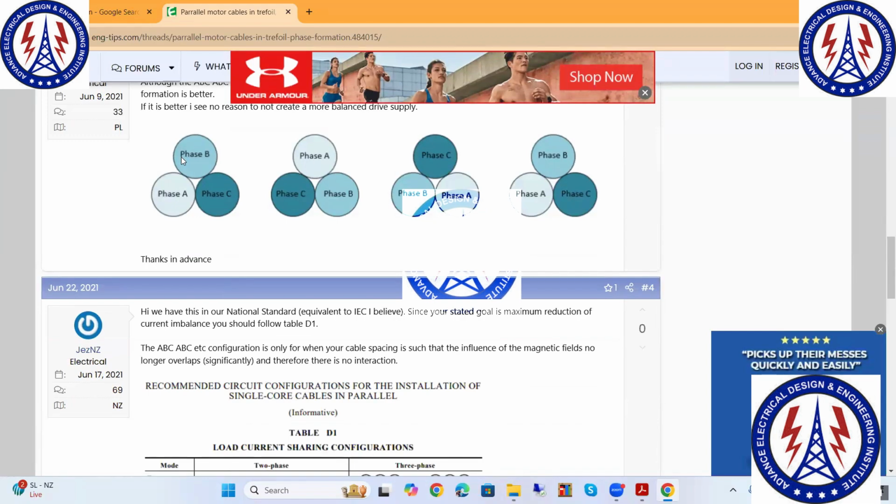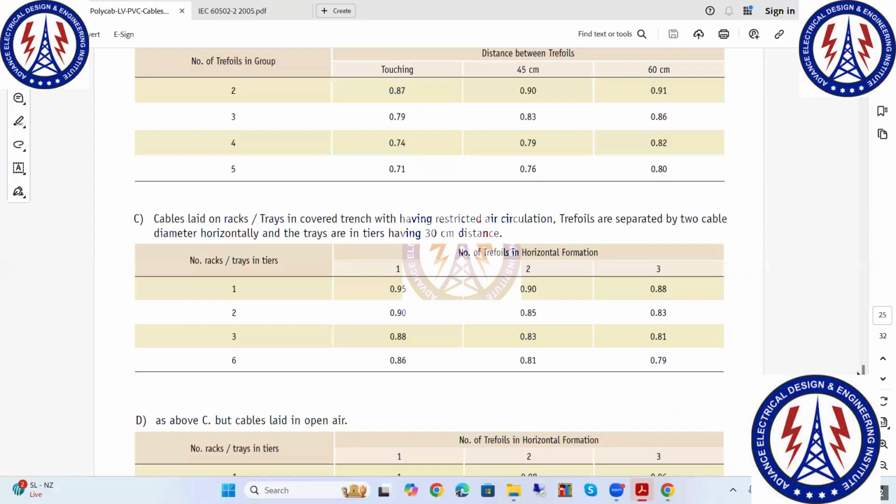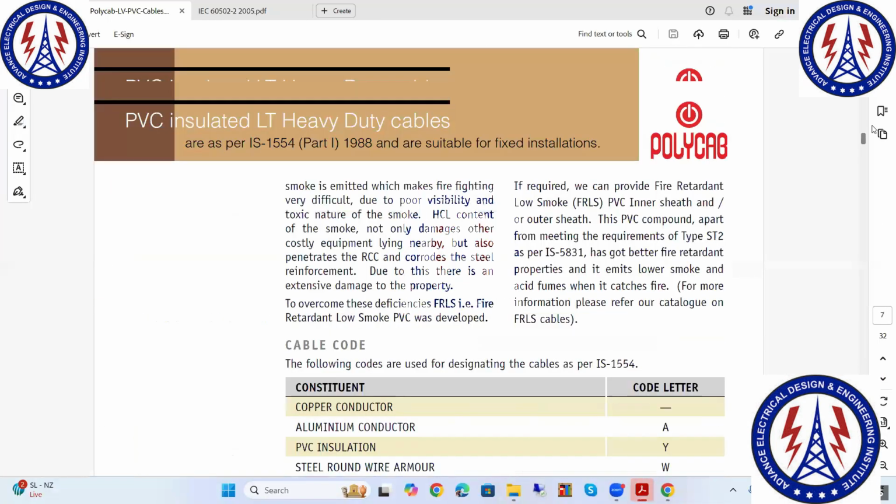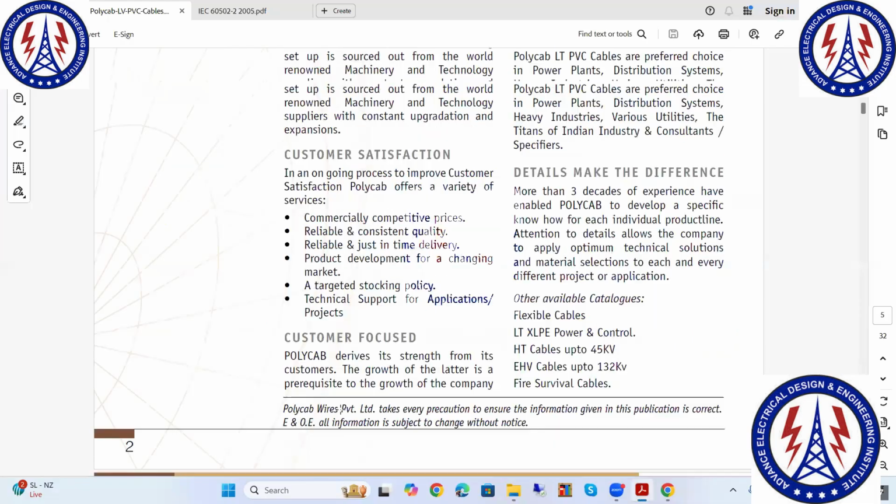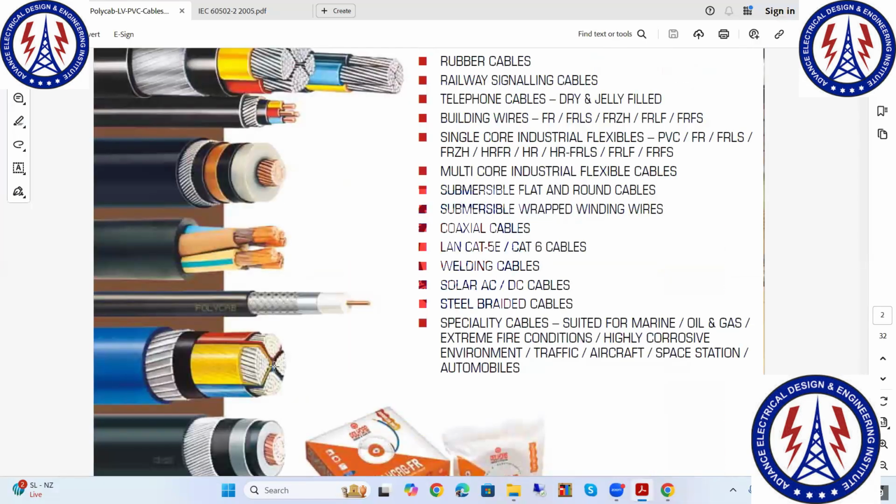Okay. So basically, we are distributing the phases. One set will be made like this. Let me come to the multi-core cable. In multi-core cable, we are already making it like this. Cables are rectangular, so it is already in that shape. For the single core cable, we make this shape by laying the cable in this condition. So it will be like this.